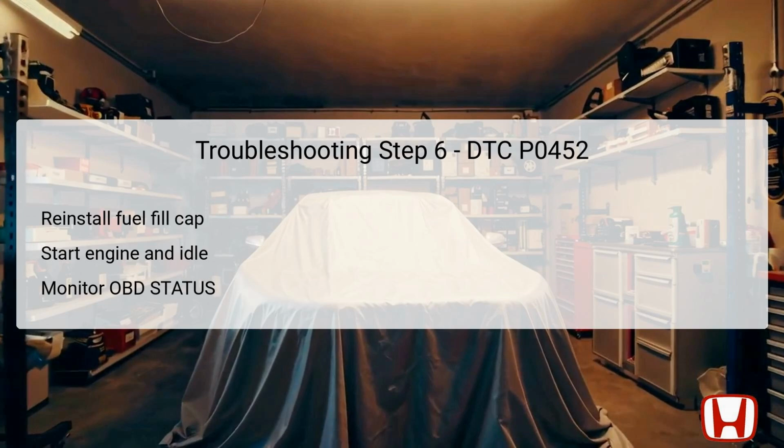During this idling period, closely monitor the onboard diagnostics OBD status for DTC P0452 using the HDS. The OBD status will provide crucial information regarding whether the DTC has failed or passed, indicating the effectiveness of the troubleshooting steps taken thus far, as well as the operational status of the FTP sensor and related systems.